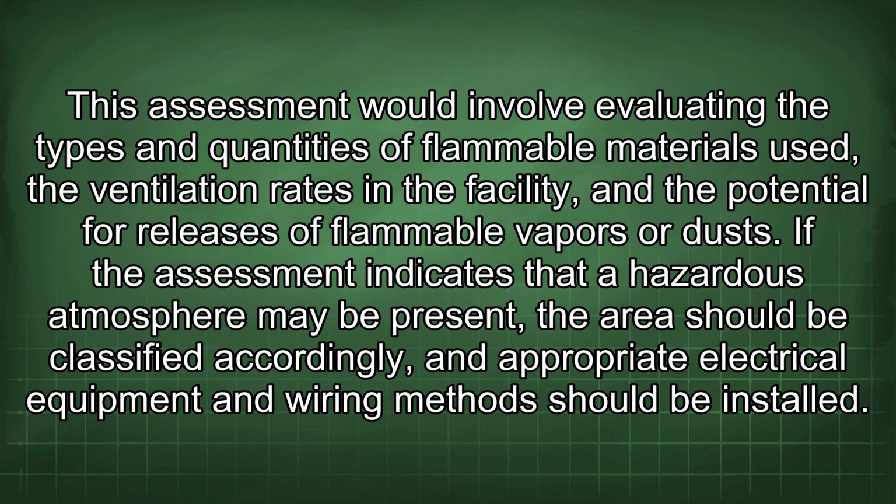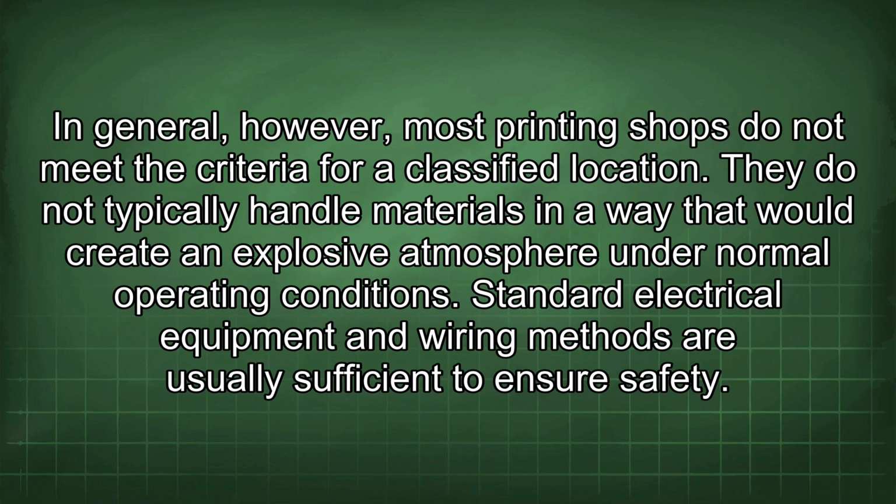If the assessment indicates that a hazardous atmosphere may be present, the area should be classified accordingly, and appropriate electrical equipment and wiring methods should be installed. In general, however, most printing shops do not meet the criteria for a classified location. They do not typically handle materials in a way that would create an explosive atmosphere under normal operating conditions. Standard electrical equipment and wiring methods are usually sufficient to ensure safety.